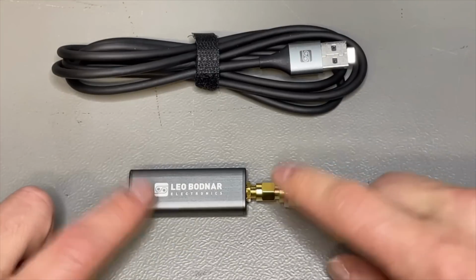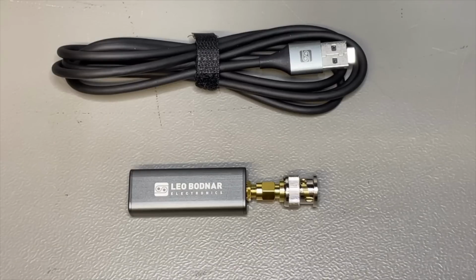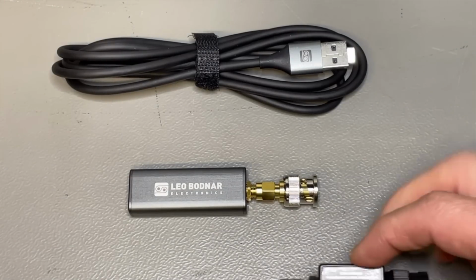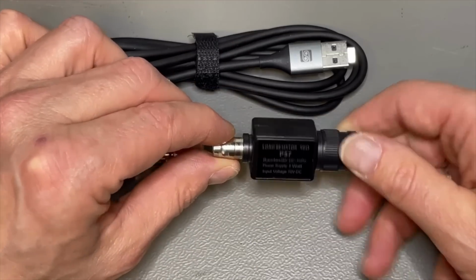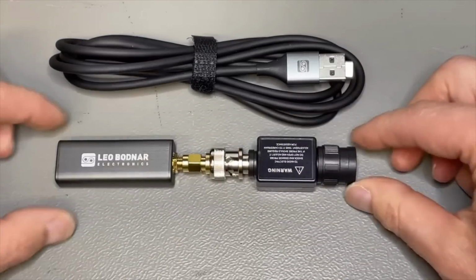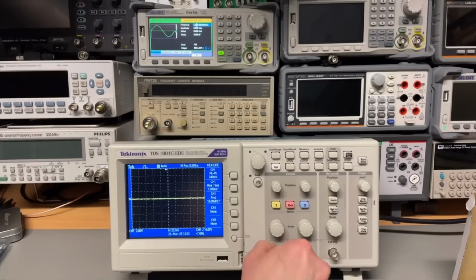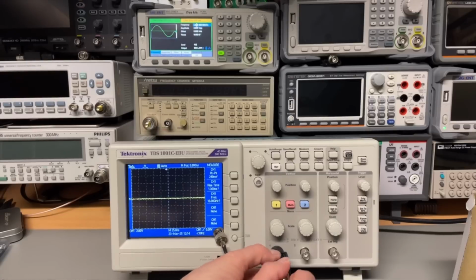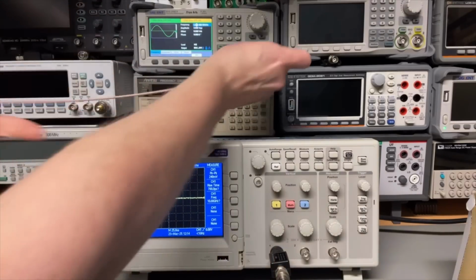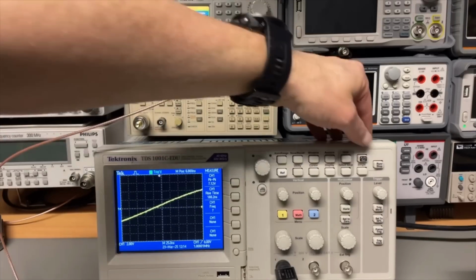We are talking RF stuff, and it is 10 megahertz. So the voltage that comes out is around 1 volt, but only when it is connected to a load of 50 ohms. Well, the oscilloscope has a 1 megohm input impedance, so I have here a pass-through 50 ohms. And we can connect it like this to the oscilloscope. Let's first try the minus 3 dB or the 70%. I put here my 50 ohms. I will do that directly in the signal generator here. I will do 1 megahertz. Here we go.